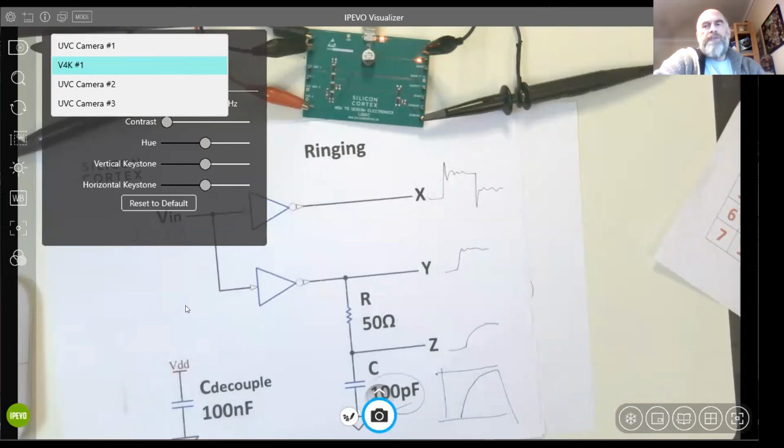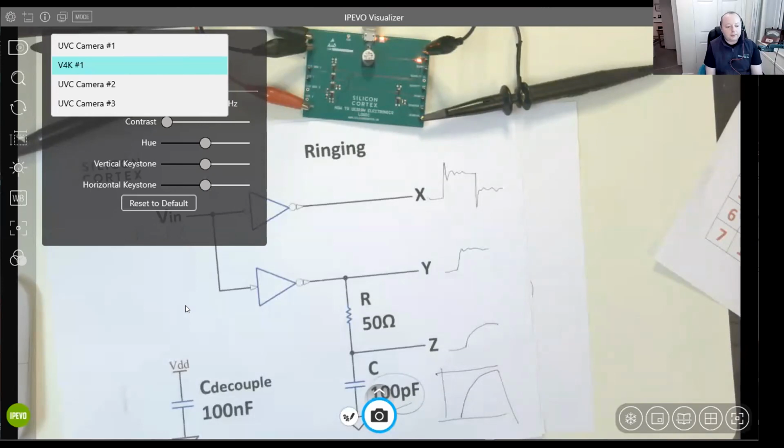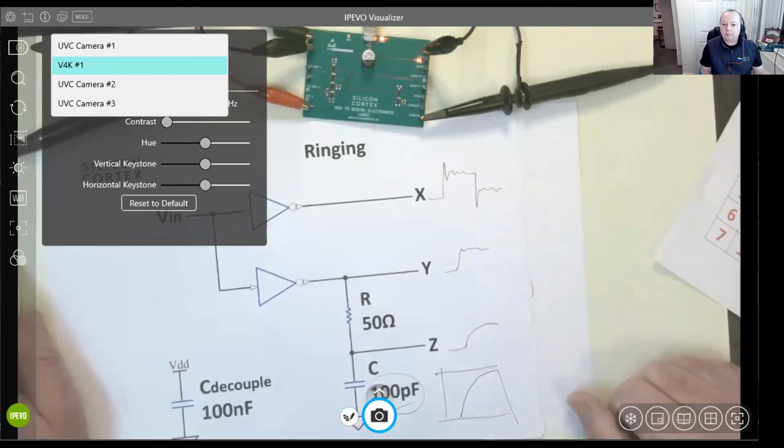In this case, it's just a battery voltage that I'm sensing directly, so I don't need any input transducer. It is already a voltage. Oh, okay. So the things you want to put on the line are probably just suppression devices, ESD suppression. In fact, bear with me a second, I might be able to find one here and share it with you.